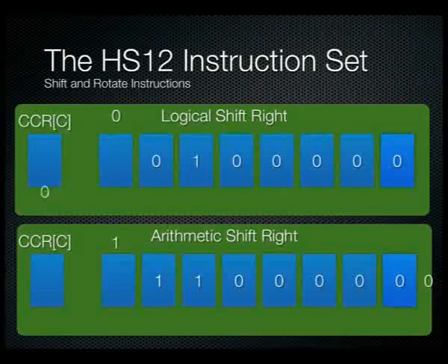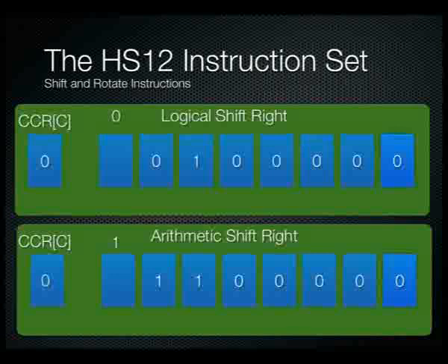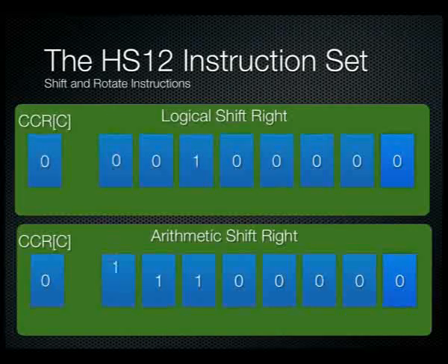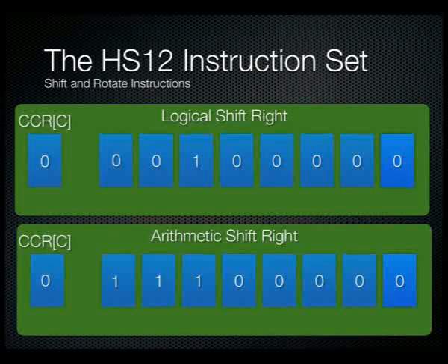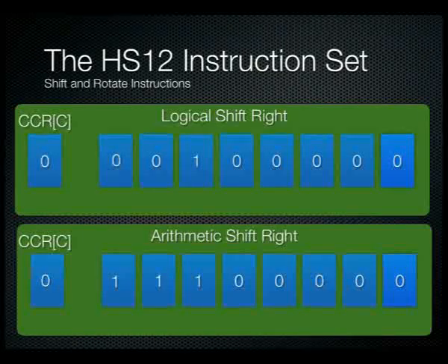So we'll do that again. The LSB slips off the end, goes to the condition code register, and then of course we insert the respective values in the MSB. Because the arithmetic value was negative, we're simply putting the 1 back in its place. If it was a positive value, so if the original MSB was 0, then of course we'd be padding it with zeros each time.